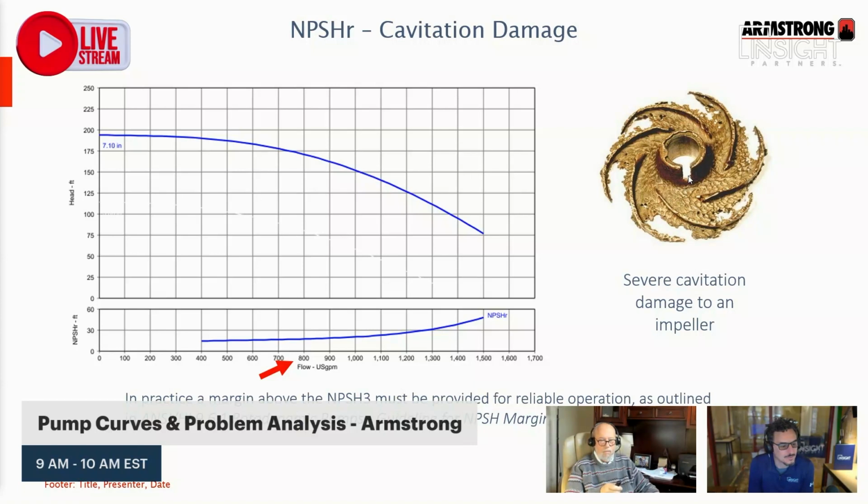PFox at Newcomb and Boyd, what is the recommended location to read suction pressure on a pump with a diffuser? Good question. So, to answer that question, I like to read my suction pressure about 2 pipe diameters before the diffuser, and then immediately downstream of the suction diffuser.